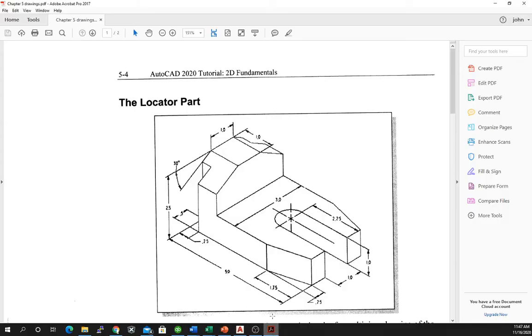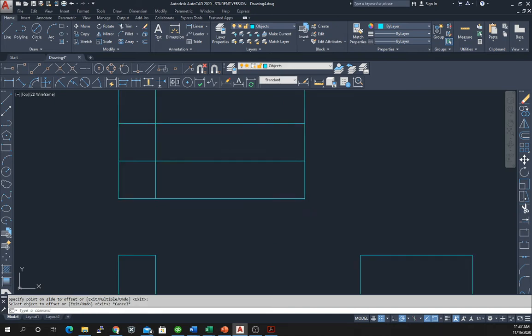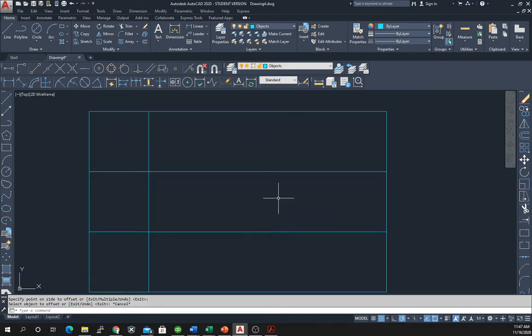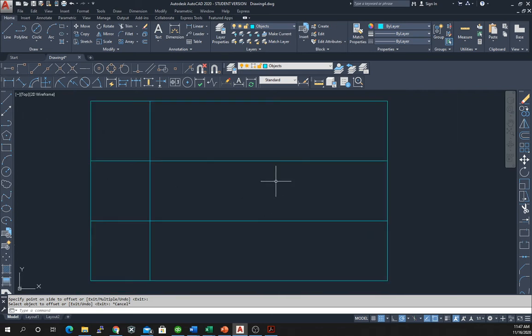Taking a quick look back at our drawing, let's put in these small cuts. So we have 0.25 inches here and 1.75, and that is true on both sides of the drawing. So let's go back to AutoCAD, and I'm going to center this and blow it up just a little bit, make it nice and big. Oh, it's a little too big. I'm going to choose line, and I'm going to hover on this point.